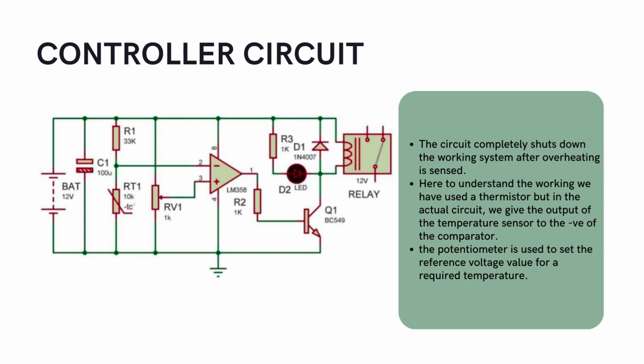For example, if the temperature of our inductor coil is less than the required temperature, then we get a high output and the relay switch will be switched on. So the circuit will be complete and current will be flowing into the heating circuit. But if the temperature crosses the required temperature, then we'll get it low and the switch will open, thereby stopping the current flow. And the switch will be closed only when the temperature of the inductor again goes below the required temperature. So in this way, we're ensuring that the temperature is maintained.